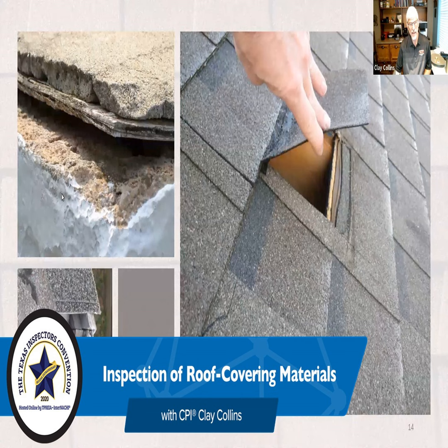Number of layers. You're not required to report it, but if you can tell there are multiple layers, I would absolutely report it, because some insurers will not insure roofs that have multiple layers. Some will do 2 layers, none will do 3.